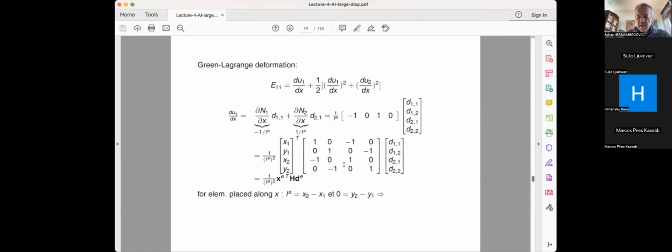And this matrix H is equal to a unit block identity matrix, so it becomes 1, 0, 0, 1, and then again the same block here, and here the same identity multiplied by minus 1. And all this is divided by LE squared, so this way I get my corresponding value of du1/dx.